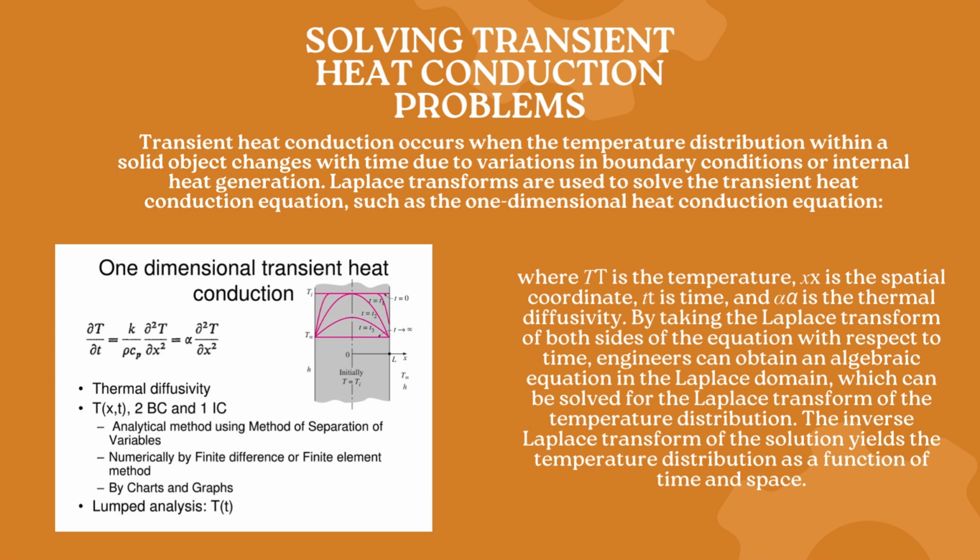By taking the Laplace transform of both sides of the equation with respect to time, engineers can obtain an algebraic equation in the Laplace domain, which can be solved for the Laplace transform of the temperature distribution. The inverse Laplace transform of the solution yields the temperature distribution as a function of space and time.